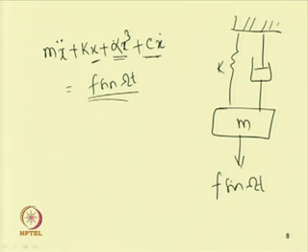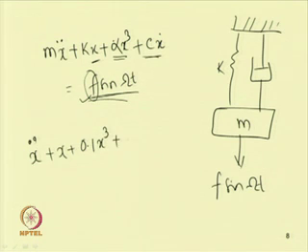Similarly, this forcing term also we can have in some situation where the forcing is one order lower than the linear term, that is, the amplitude of the forcing will be very small. Then, taking some numerical values, I can write this equation as x double dot plus x equal to 0.1 x cube, and also 0.01 x dot. If I write f equal to 0.1 sin omega t,